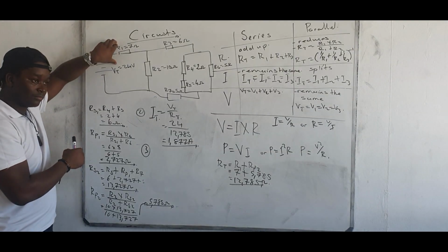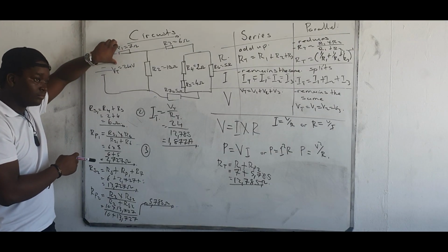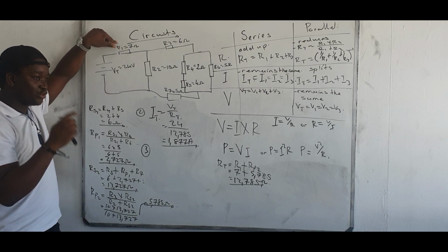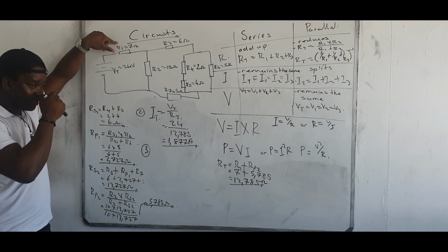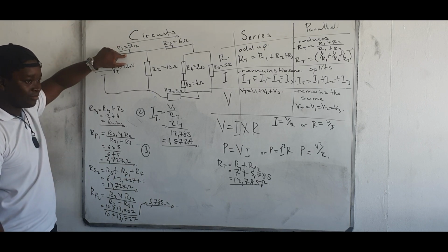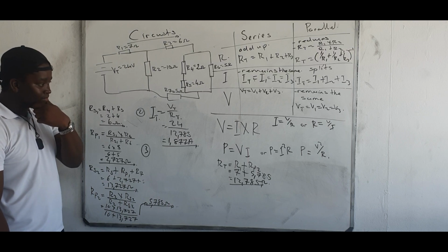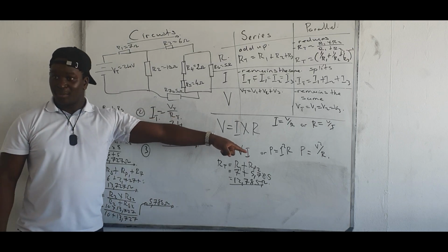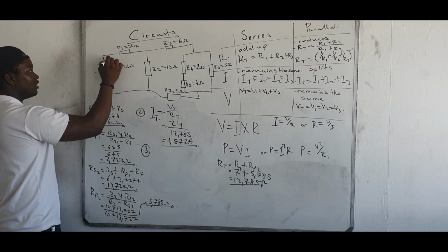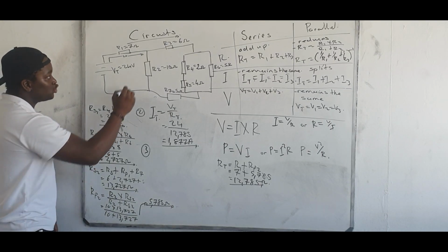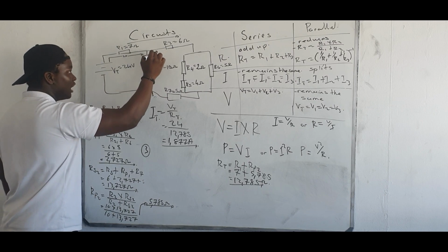You have to go to the first one and find the resistance there. The resistance is given, so it's I squared R, right? Because this is our total current, and our total current is going to pass through R1. It needs to split after that.